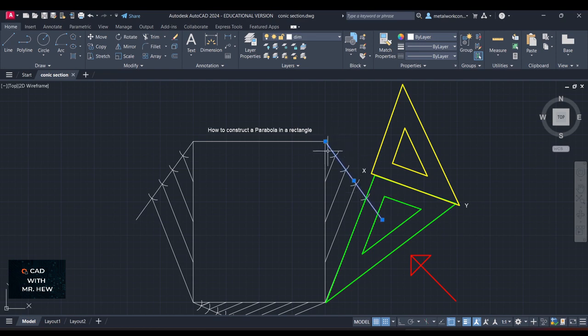So where these arcs intersect, this highlighted blue line, you would slide the green 3060 set square along the edge of the 45-degree set square labeled XY to get the lines parallel from the original one that you had joined in the previous step. Right, so that is how you would use two set squares if you were using the traditional instruments to draw a parallel line.